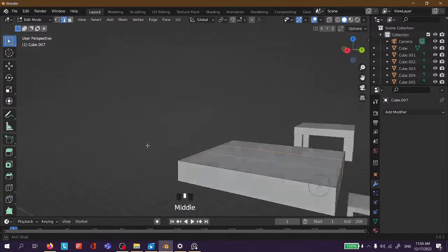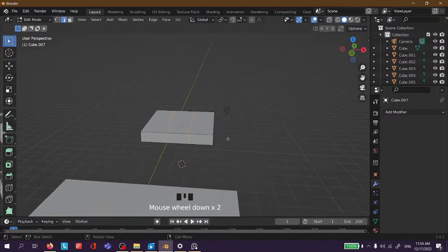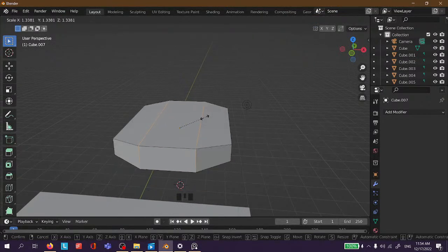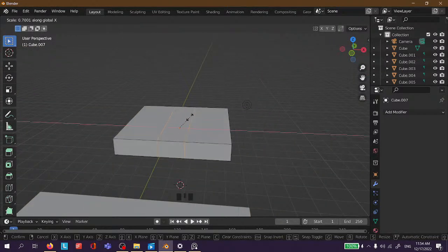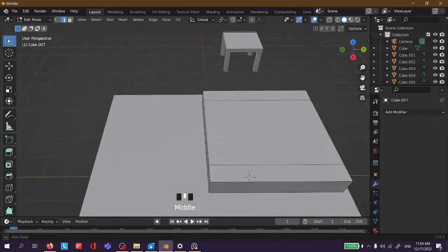So if you want to move them towards the side, we can actually just use the scaling tool. So press S to scale, and we only want them to move on the x-axis. So we press X and you can see it smoothly slides now. So just place them near the edge where they look kind of good and left click to release.